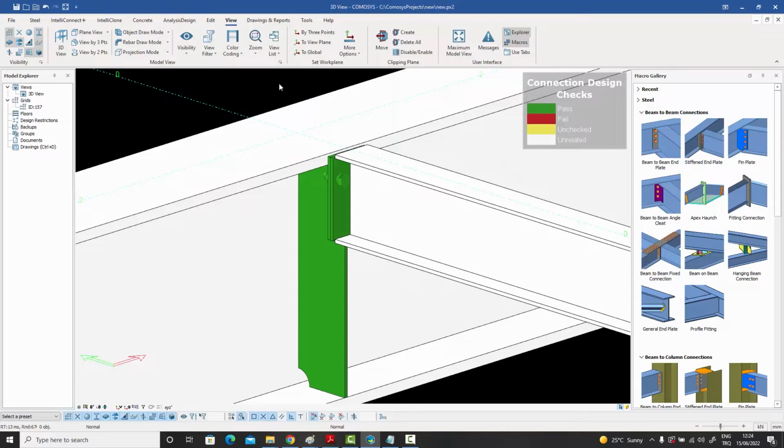But now I'm going to show you something where this preliminary design fails, because this just does a very simple check of basically dividing the load by the bolt's allowable shear. For example, it doesn't do a block shear check, which can cause other different types of failure. It doesn't do that in the preliminary, but it will do that in the final report, and that's where you're going to find out.